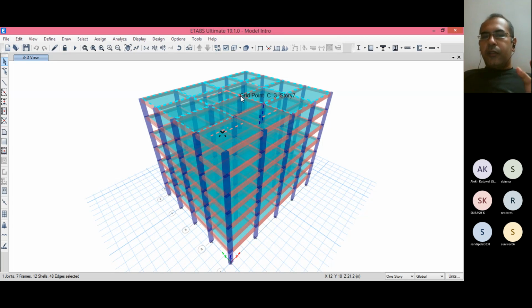But when you give a semi-rigid diaphragm, the solution becomes difficult. So we cannot do it manually. We have to follow the tributary path, so that becomes complicated. Right now we will see only that part, how lump mass modeling is done, because we have a slab of 125 mm which is rigid, and hence we have given it as a rigid diaphragm.